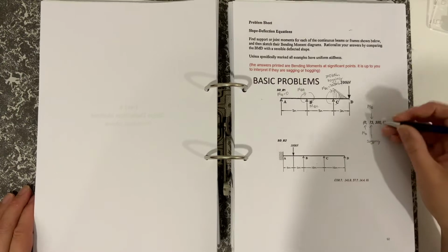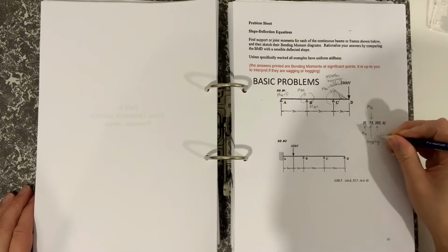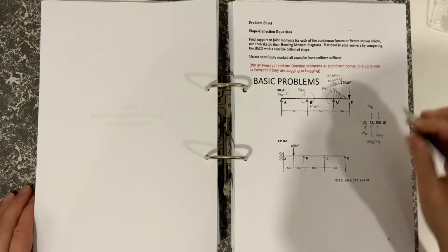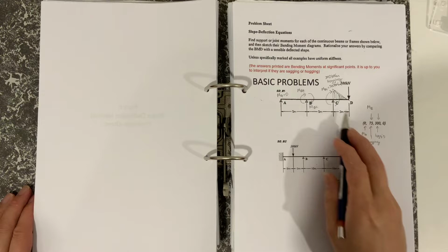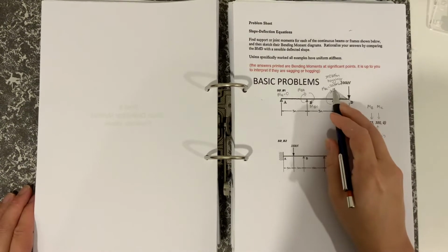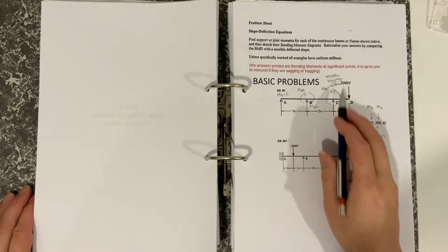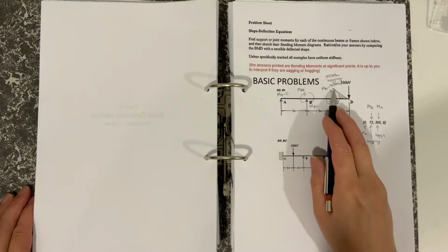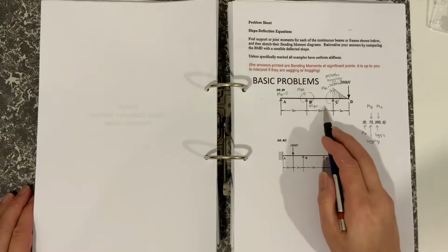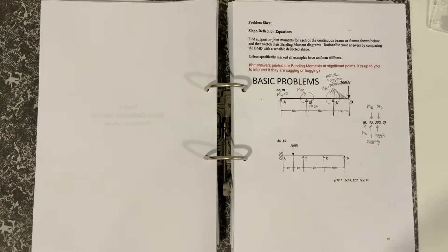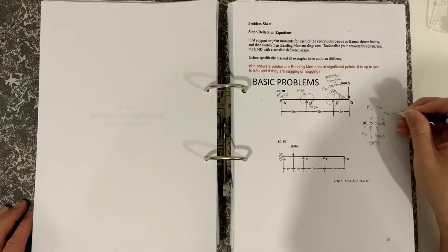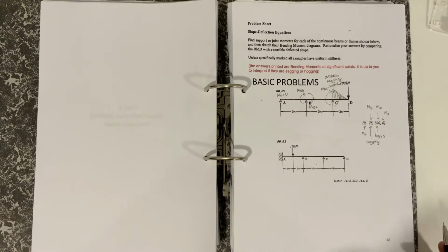And then up here we've got that one as hogging, and this one here as MC. So MC, the bending moment at C, is going to be 300 kilonewton meters hogging, and we can see that the arrows here would be in the hogging direction. So that's the thing that you need to resolve before you do the calculation. And of course, right at the end of the cantilever, MD is going to be 0, which is what you would expect.